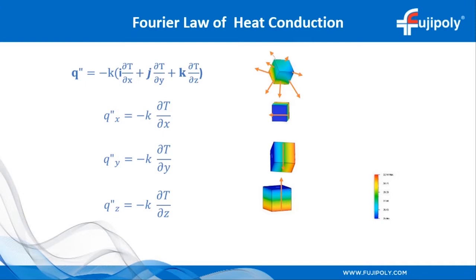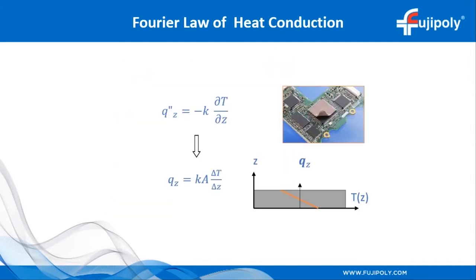Here's Fourier's law shown in its differential form. It can be broken down into three vectors, one for each axis. Our material conducts equally in all directions, but in-plane conductivity is negligible since the heat will want to take the shortest path of resistance, and that's always going to be through the z-axis. So since we only need to concern ourselves with the scalar value of the heat flow, what we want to do is isolate the heat flow through the z-axis through a specific area.